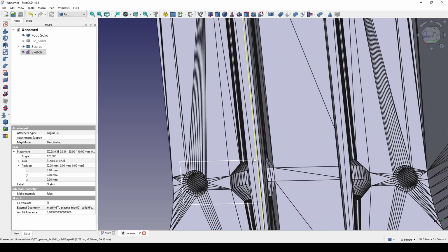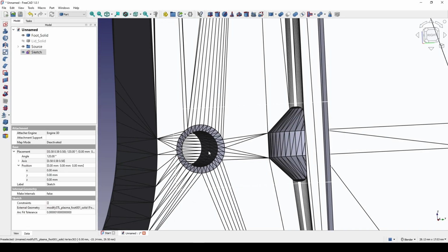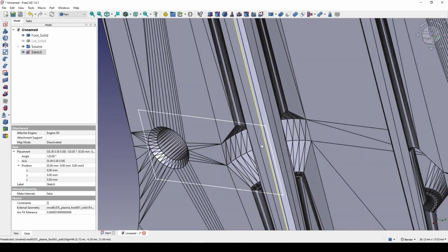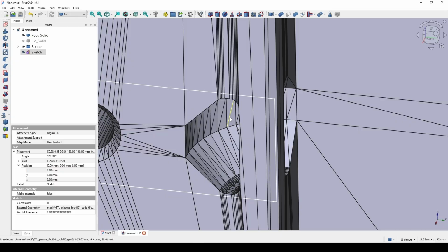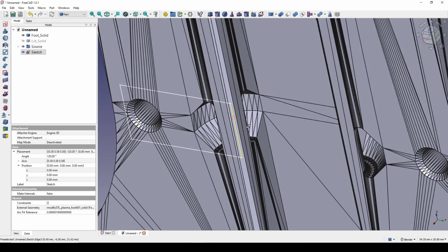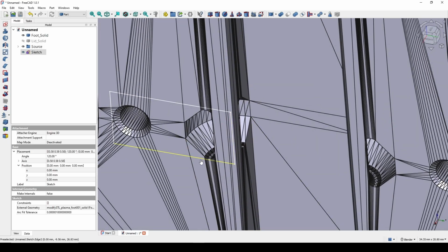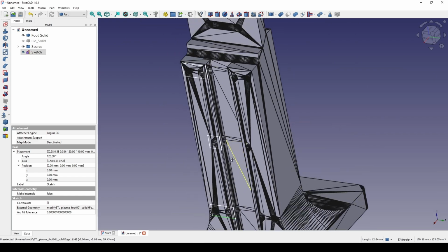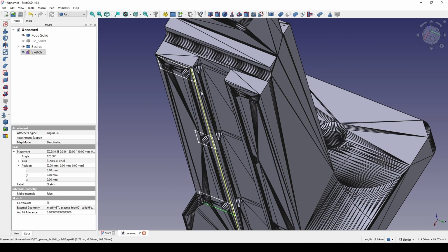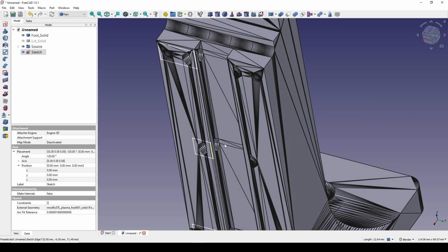And you can see one is a hole with a chamfer up here. This one is a hole, but they are using a revolution in here to cut around the geometry. So I'm going to extrude this rectangle inside the solid, and then union to remove these guys.